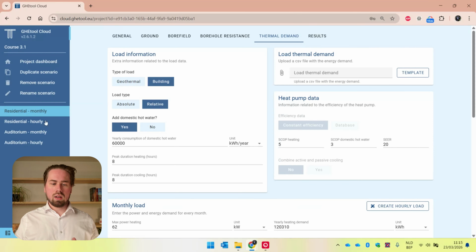So that's why we need this estimate, this mathematical concept of a peak duration, which is best described as: if our heat pump turns on at maximum power, or the maximum power of the month, how long will that power be there continuously? Now, of course, this is a sort of estimate because you cannot really know how long it is.